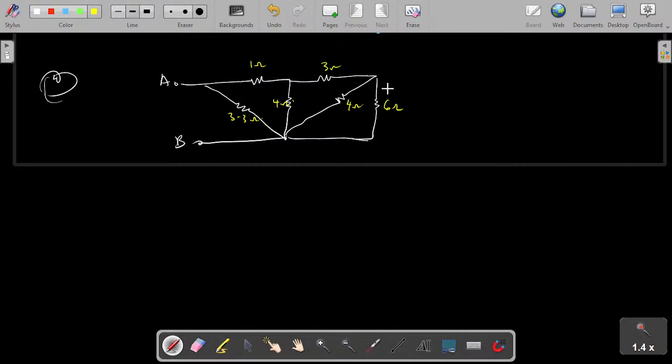Because of that, you come to the far end. At the end of the terminal, I can see my first two resistors, which are 4 and 6 ohm, right? You ask yourself, are they in series or in parallel? There is a node here, there is a node here. That makes it not in series. But let's see if it is in parallel. You need to traverse through their paths like this, and once you do, you shouldn't meet any other element aside from these two resistors. And that makes it what? Parallel, right? So we can say that 4 ohm is indeed parallel to 6 ohm.